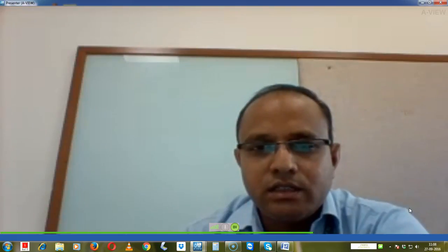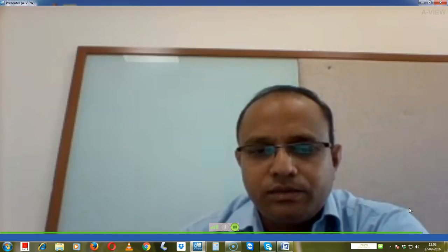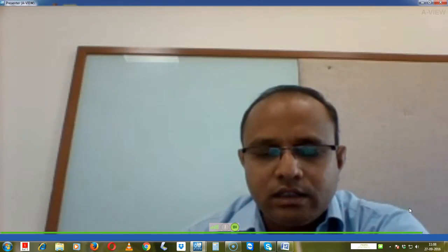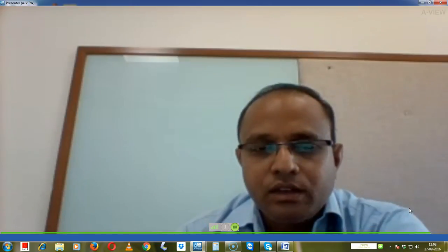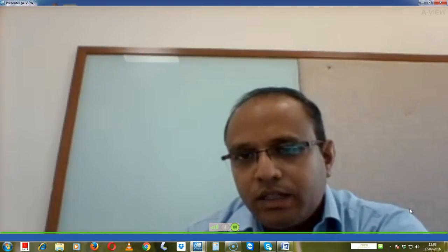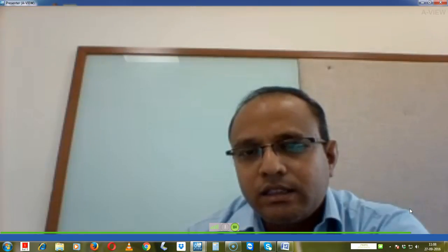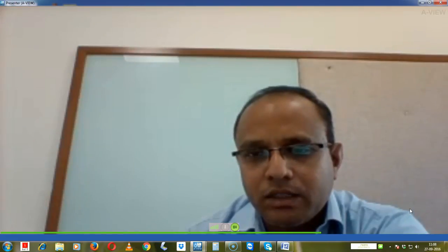If you see here, this is a radial deflection plot. RCS 1 is a cylindrical coordinate system, and UX is the radial deflection. Here, if you see, it is free. The rotor is freely expanding as it moves from inner to outer diameter. The inner diameter has maximum expansion and the outer diameter has less expansion.